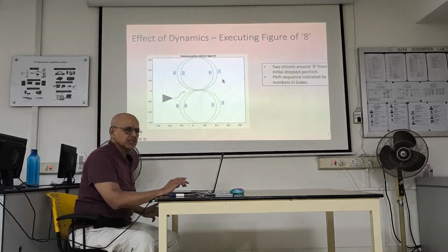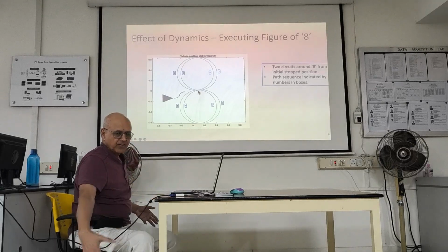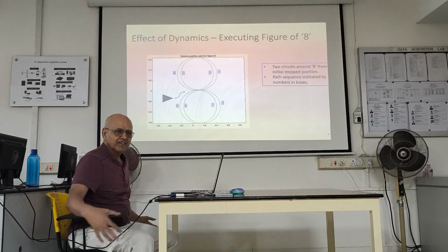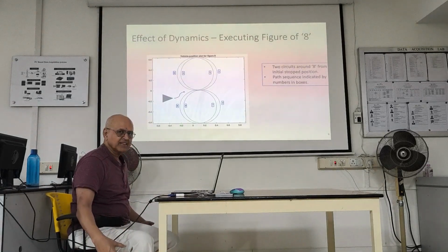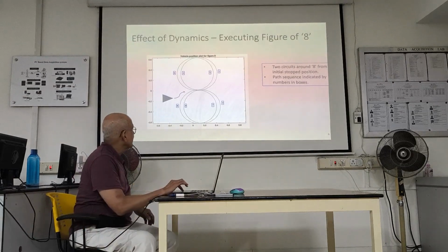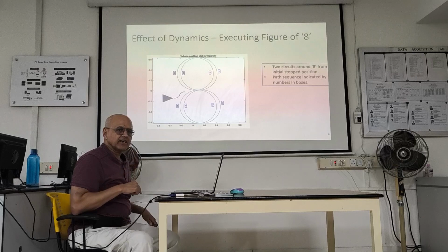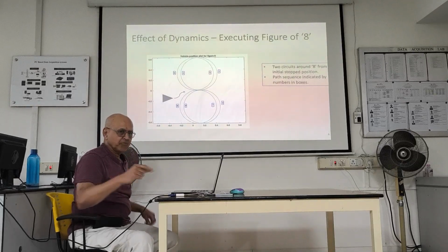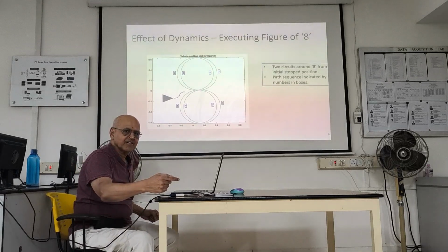So you know what the explanation is for this? Initially you're stopped, right? So right wheel velocity. This is where the motors are connected. V doesn't have a motor. So V right and V left, V1 and V2, right? They are both stopped. So to go counterclockwise around the vehicle, the right wheel has to get to a higher target velocity. Both are at 0 now. But the right wheel has further to go.